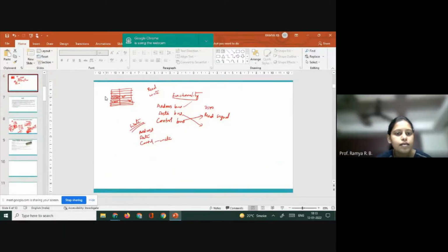Aditya, when you have some data stored, you can do both read and write operations. Suppose you want to access a particular memory location. Memory is nothing but a series of locations, and every location will have an address of its own. How do you identify a location? By its address. So if you have address 3500 and some data stored there, say 45, and you want to read that data, say 45.